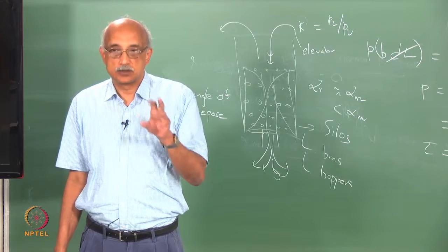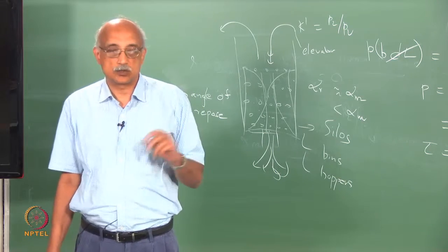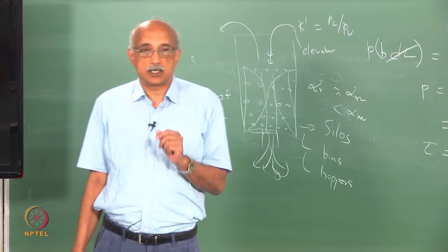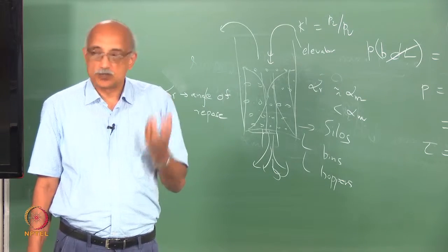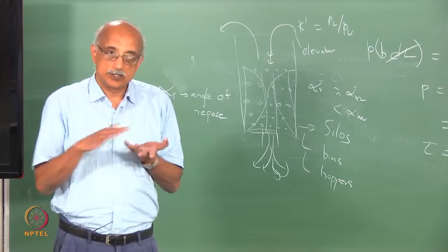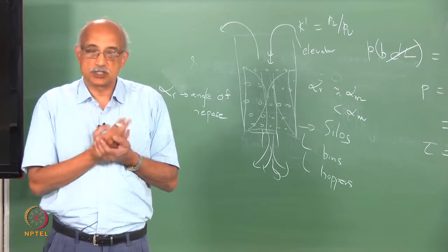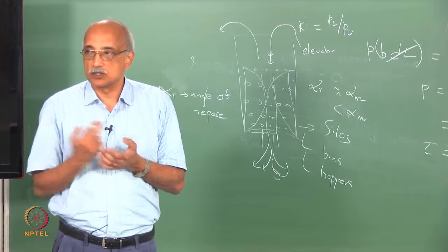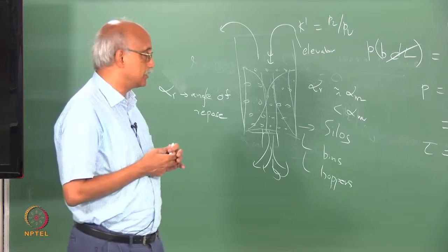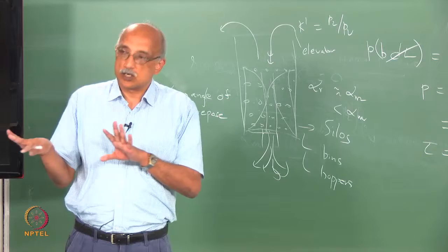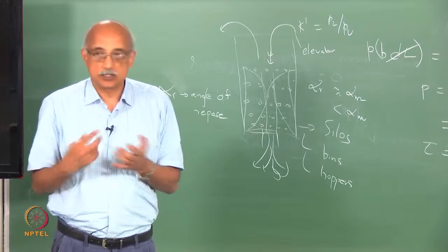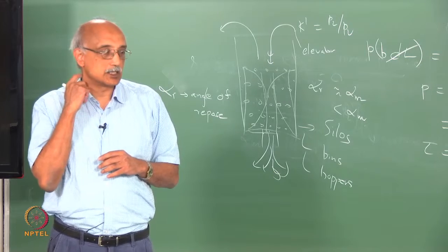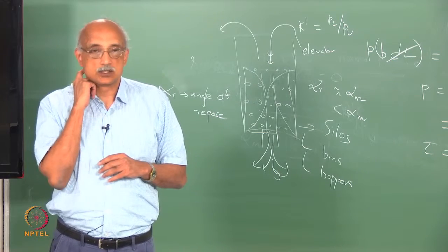Unless you have active humidity controls in your storage chamber, it is very likely that the humidity will be absorbed by the particles and they will start forming these liquid bridges and the solid bridges that we talked about earlier. Once that happens, material that was originally non-cohesive can over time become cohesive in nature, and therefore its flow characteristics will start to change